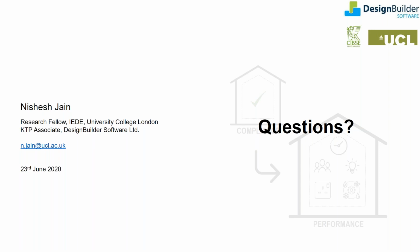And to be honest, linking it to the first question, one of the uncertainties is weather. CIBSE is developing tools for overheating analysis, etc. You would want to model future weather files, and this is something TM54 also advocates, that you can do a stress assessment of weather scenarios under climate change, how things will change. I think the climate analytics tool will provide you with a good amount of data for realistic locations, projections, what has been recorded, and what the base files are. So all these things are quite intertwined, I would say, and add value to your overall calculations.